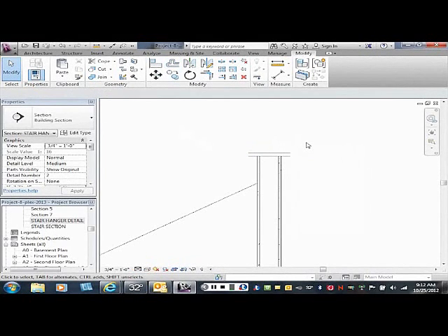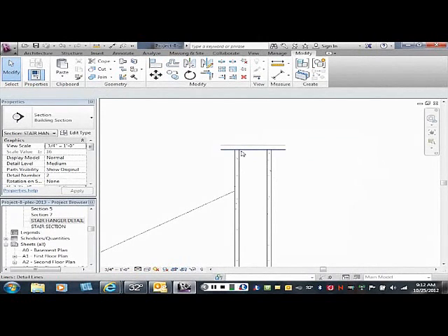And is it going to be a 1x6, a 1x8, a 1x4? Well, that's not important really. What they're going to do is they're going to make a board that fits this wall. And our wall is 4.5 inches, right? So if it was a 1x6, it'd be 5.5 inches. It would hang over 1 inch on each side.